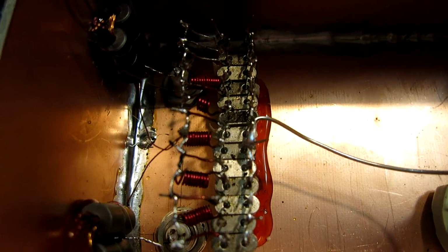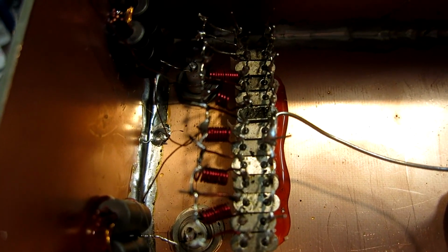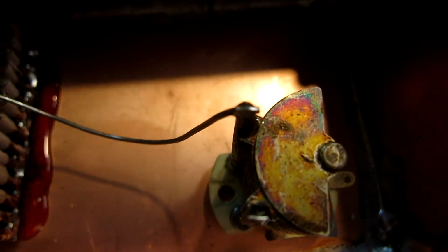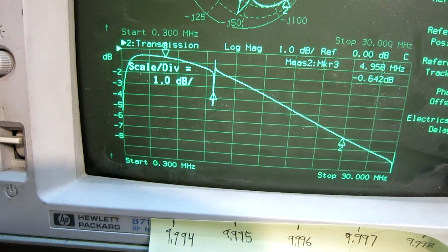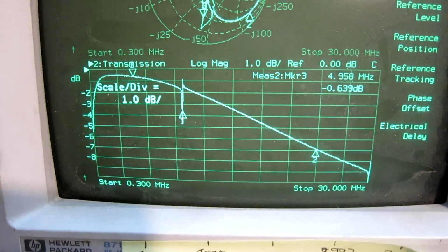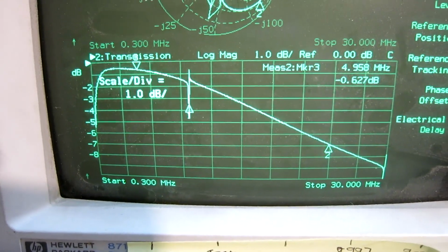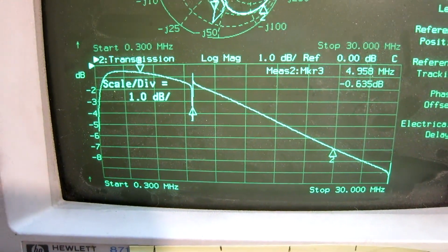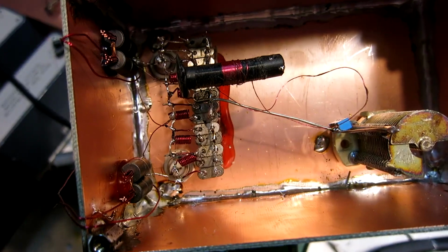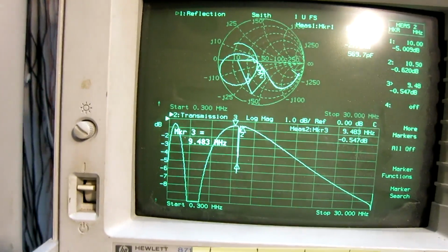These crystals are adjusted to a common resonance frequency, and I have connected them from the 450 ohm point here to a capacitor to ground. And this is what I see now on the network analyzer. This is the capacitive load from the, what do you call it? The capacitance of the crystals. I have to balance that by an appropriate inductor. Something like this. Then this is what I see.